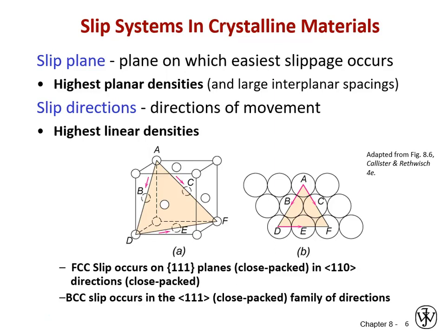We discussed redundancy of slip systems possibly when we discussed defects, but we'll do it again here. If we didn't, we'll catch it. If you remember your body-centered cubic unit cell, the close packed directions are any direction that goes through a body diagonal. And there's a lot of equivalent body diagonals. So although they don't represent close packed planes, and therefore compared to an FCC crystal they're going to require a little bit more stress to get those dislocations moving, there are a lot of different directions that dislocations can move that are still close packed directions.